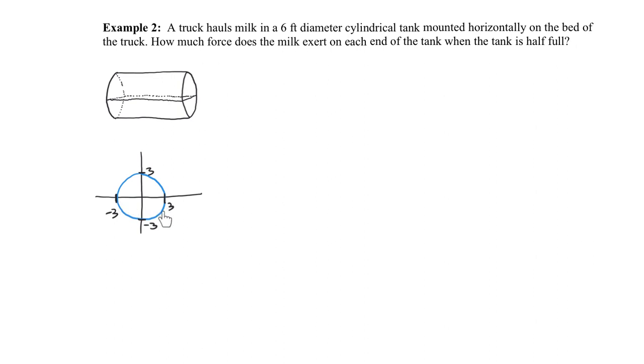All right, so this thing is half full, so basically this bottom half is all full of milk, right? The bottom half is all milk in here. So maybe just kind of draw so that this is all milk here. And we want to figure out the force against this side of this. So we can do what we did in the last one. I'm going to basically just draw in a little sample slice here, a little rectangular piece. And then I'm just going to find the force against this sample strip, and then integrate wherever these strips are.